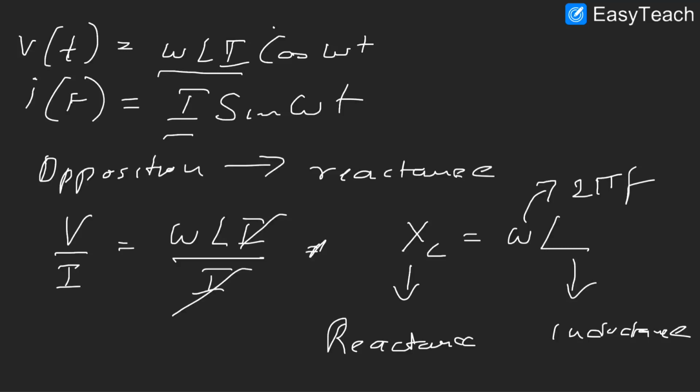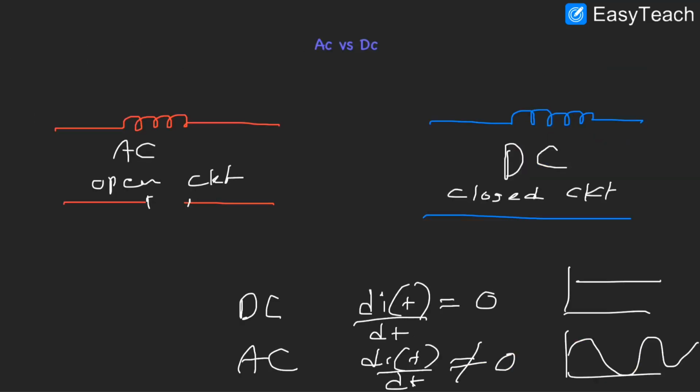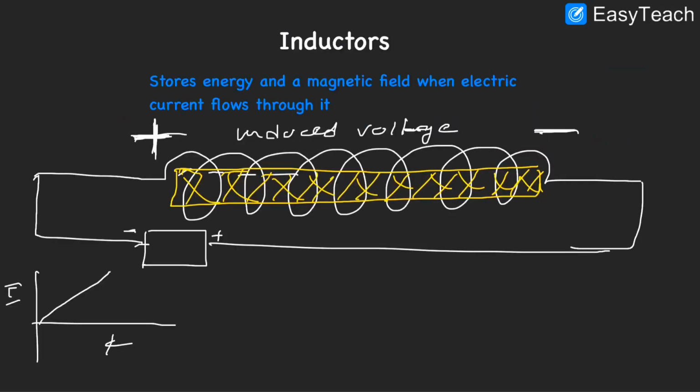That is it, guys. So let's review from the top. An inductor is just a piece of conductor, usually a copper wire, wound around a core. This is sometimes an iron core, sometimes it's just an air core, and this conductor has to be insulated when it's wound.